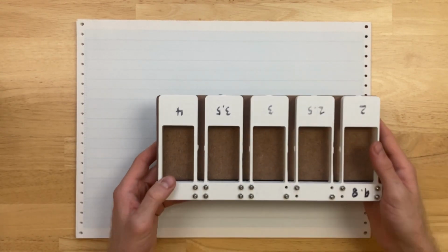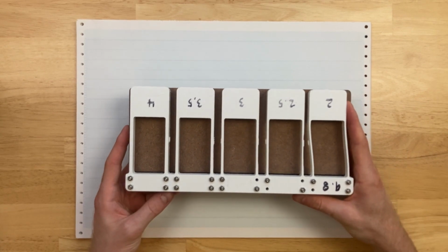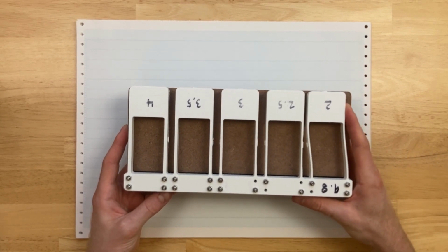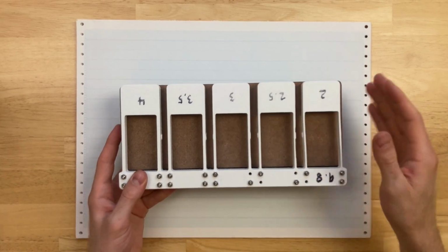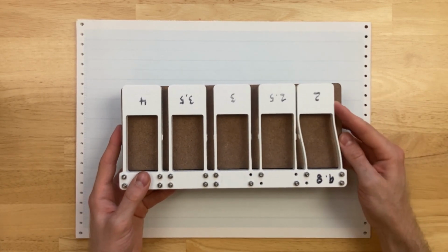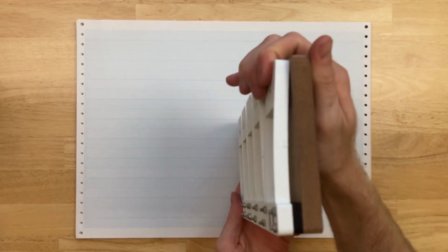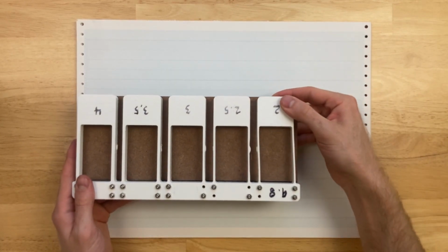This is another set of parallelogram flexures, and you can see that it has this very nice S-shaped bending to it. It's not cantilevered, it's definitely moving in that wiggle in plane. However, out of plane, it moves in C-shaped bending. It is cantilevered out of plane.